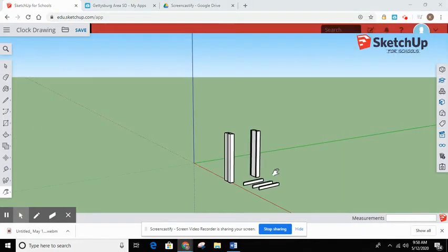Moving on to component C. Component C, these numbers again are from your drawings. They are 6 and 7/8, so the same length as B's. They're a little wider though. They're 1.5 inches. Thickness is the same at 1/2 inch, and they also get 1/4 inch rabbets on the end. So they're very similar to B's. So I'm going to work smarter, not harder here.